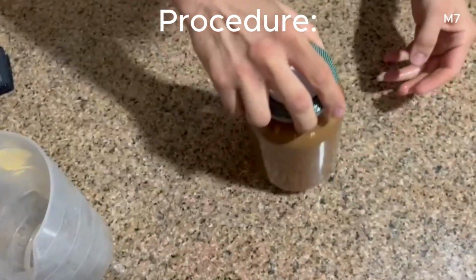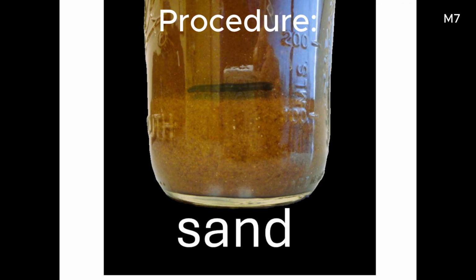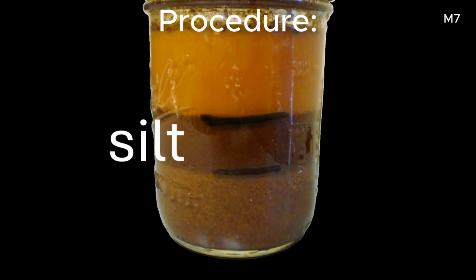5. Set on a level surface and time for 1 minute. 6. Place a mark on the outside of the jar, showing the coarse sand layer settled at the bottom of the jar. 7. Leave the jar in a level spot for 2 hours. 8. Mark the top of the next settled layer with the permanent marker. This is the silt layer.